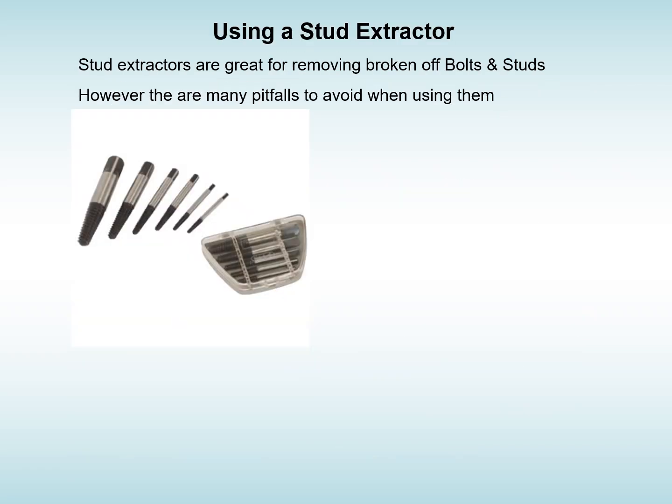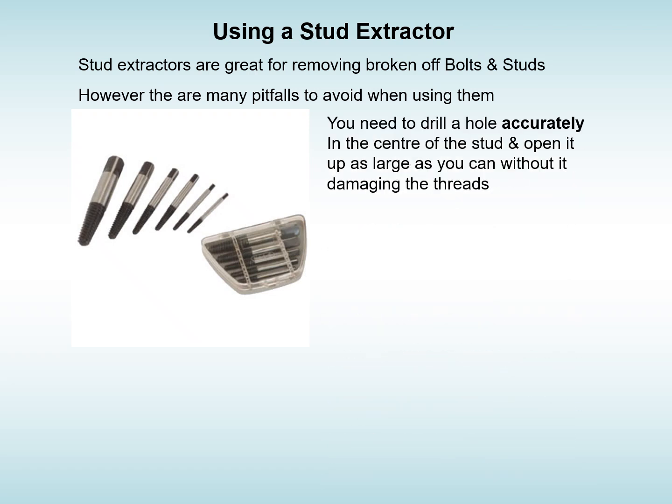Using a stud extractor, if you break a stud off or a bolt off within a casting or something, then the stud extractor is generally quite good for removing bolts and studs. However, there are a few pitfalls to avoid when using them. One, you need to drill the hole accurately in the centre of the stud and open it up as large as you can without damaging the threads. And it's quite important to get it as wide as you can.